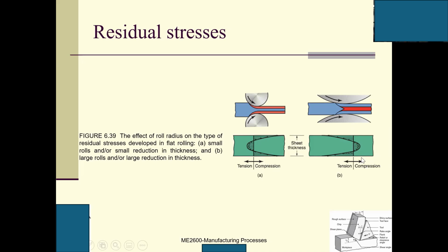The last time I told you, in terms of fatigue life, what kind of residual stress is good and what kind of residual stress is bad. Yeah, compressive residual stress is good, because compressive residual stress always prevents cracks from initiating and from propagating.